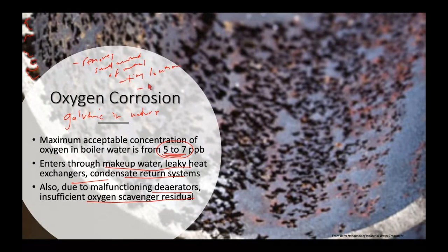And then basically it turns our boiler into Swiss cheese. Okay? And I don't know about you, but I don't like Swiss cheese. So I would say this stuff here is the #1 killer. And in case you didn't know, I was a boiler inspector for 7 years. And I would call this #1 killer of boilers oxygen corrosion. So keep those oxygen scavenger residuals up.